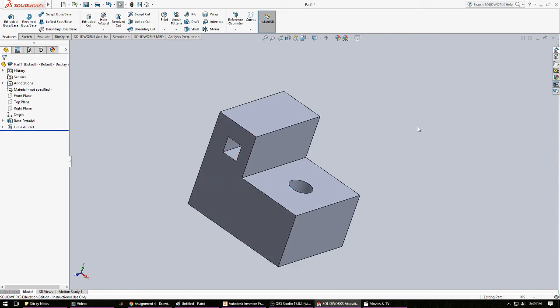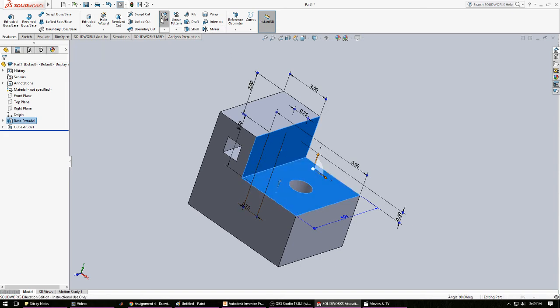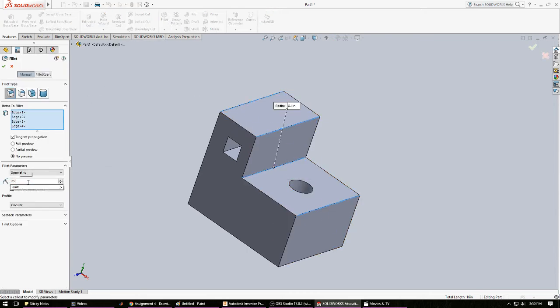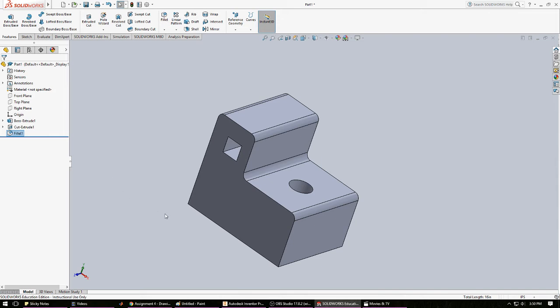And then for one last thing, for those of you that didn't learn how to use fillet, the book asks you to select a surface and a surface and then select fillet. I'm honestly not a huge fan of that approach because I think it allows for ambiguity. So we're going to fillet, let's say, these edges right here. What I do is I hold down Control and I select the edges here. We're going to fillet the edges to be a radius of maybe 0.25. And then we'll fillet that, and that looks nice. So selecting the edges is better than selecting both faces when you decide to fillet. So just keep that in mind.